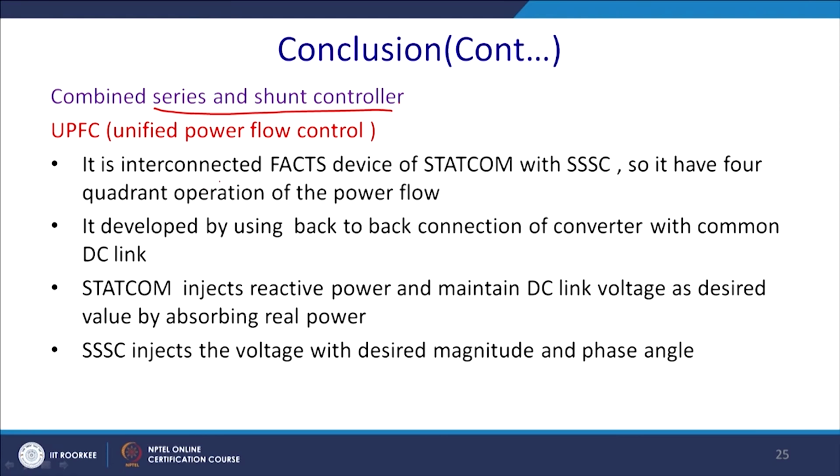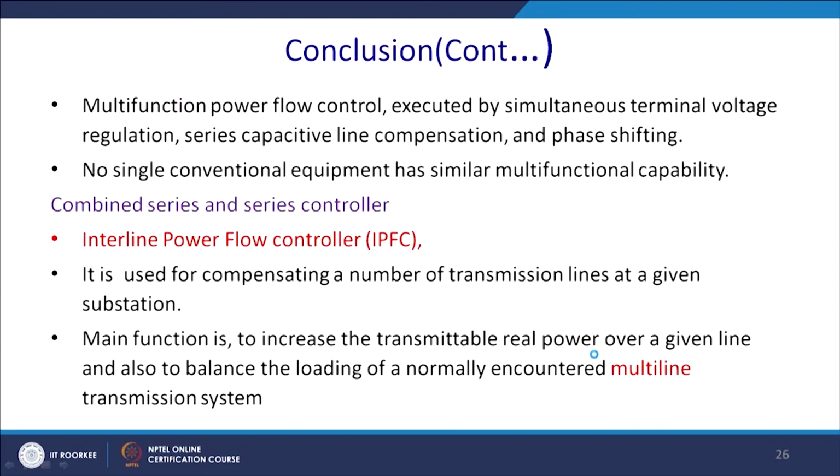It is an interconnected FACTS device, a combination of STATCOM and SSSC. So it has all 4 quadrant operations of power flow. It is developed by using back to back connected converters with a common DC link. STATCOM injects reactive power and maintains the DC link voltage as desired by absorbing real power. SSSC injects the voltage with the desired magnitude and phase angle.